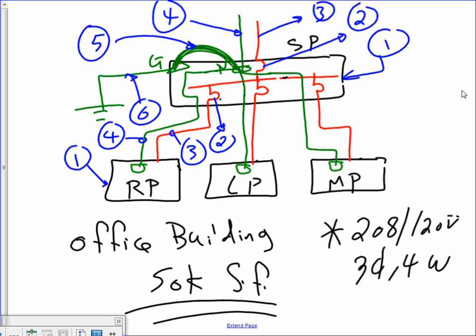We have 4 panels and our project has only 3, right? The main panel and 2 lighting receptacle. I added 1 more because that's what we typically have in the riser. And we are to size the feeders and overcurrent protection device for them, the service conductors and overcurrent protection device, service disconnect means, the main bonding jumper and the grounding electrode conductor. The main bonding jumper right here, the grounding electrode conductor that goes to the rod, to the pipe, and the equipment grounding conductor in every one of these panels.